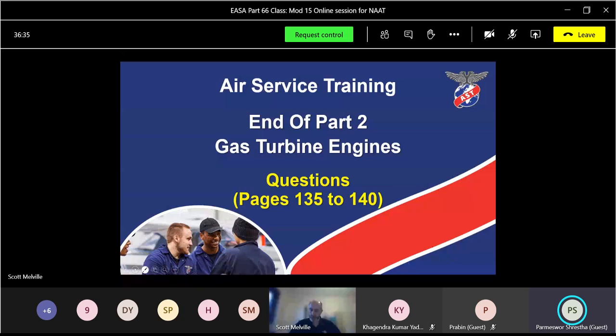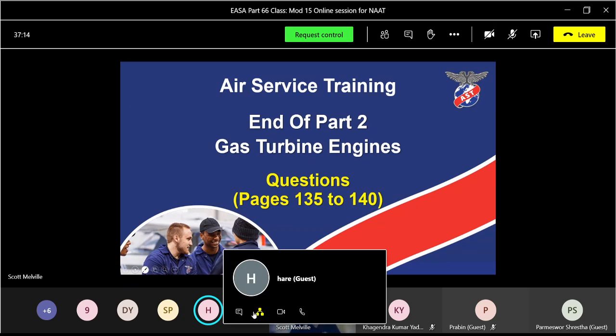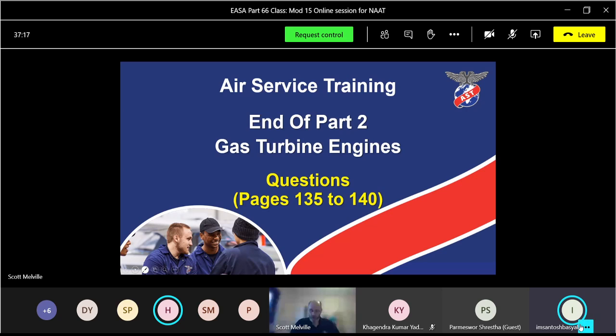Okay, I'll start with question number 4 here. What is the freezing point of jet A1? What do you think that is? Negative 47 degrees Celsius. Good, yeah, negative 47. Number 7, what sort of temperature ranges would we encounter our good friend Cladosporium resinae, nice fungus? What sort of temperatures are we looking at? 25. Yeah, sort of warm, moist. 25, 35. Okay.